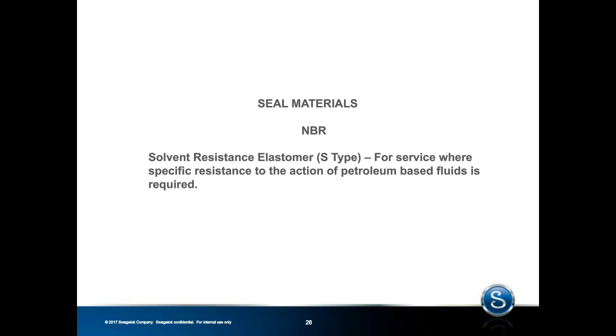So I think something that can help you keep these materials straight is to think of HNBR as almost an opposite to ethylene propylene rubber. Whereas we knew that ethylene propylene rubber is not resistant to petroleum-based fluids, this is where HNBR tends to shine as a material. So they're almost completely opposing each other in terms of chemical resistance. So you should never find yourself in a situation where you're trying to determine between the two and which to use in your process, because they would be used in completely different situations.